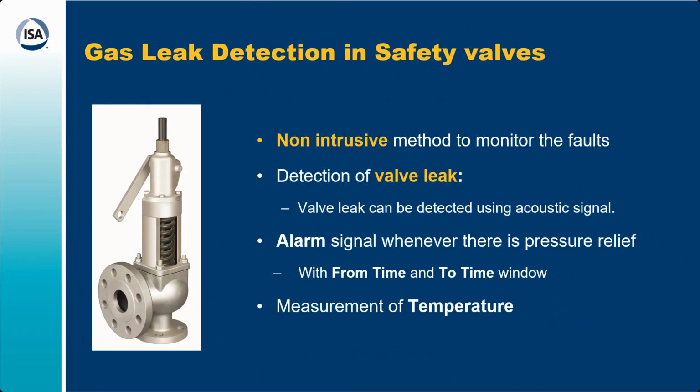Another important application is gas leak detection. You can see that in any process plant there are so many safety valves. These safety valves operate once in a lifetime, maybe when there is an alarming condition, and then the safety valve opens. But the problem with the safety valve is that if there is a leak, there is a continuous leakage through it, and you are losing either your heat or your very costly fluid which is passing through that line.